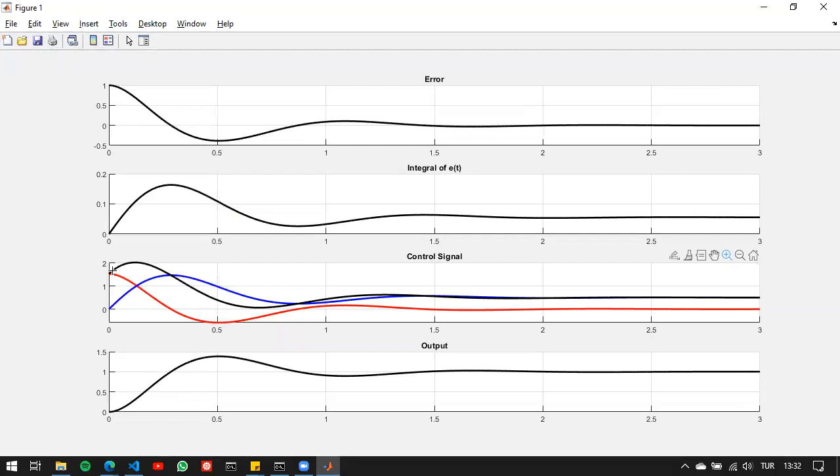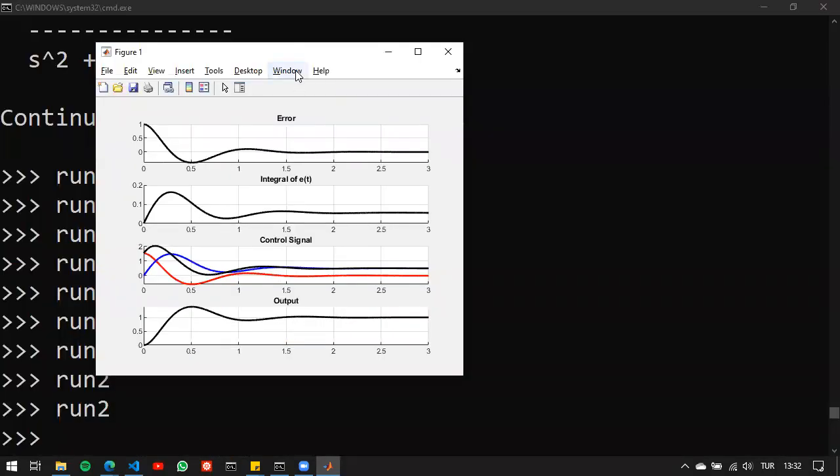And you can see that basically the p-type controller part is dominating at the beginning, and at the end, the integral part is dominating. So therefore, we can see that there's a blending between the integral part and proportional part. So you can think about the PID controller a bit different here. You can take into account that there will be derivative part, integral part, and proportional part, and they will all be acting together and will try to drive the system to the output.